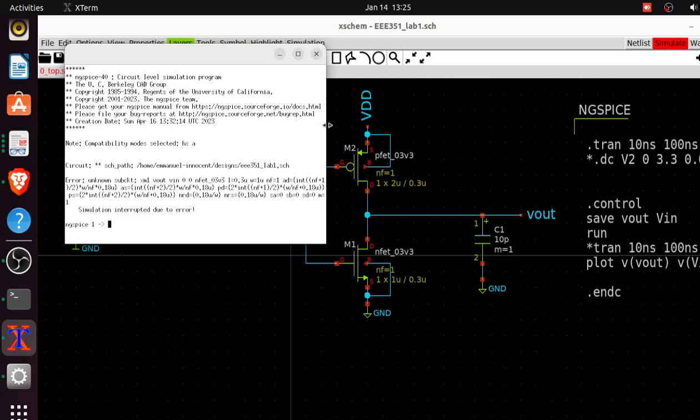That's because this is a schematic. A schematic is different from ngSpice, and ngSpice is different from the PDK you're using. So these are different party objects working together. From the schematic, you picked this component that belongs to the PDK you want to fabricate with. But when you try to simulate, there is nothing telling ngSpice where this belongs to. So to ngSpice, this is an unknown object, so you need to tell ngSpice where it belongs and where it's located.